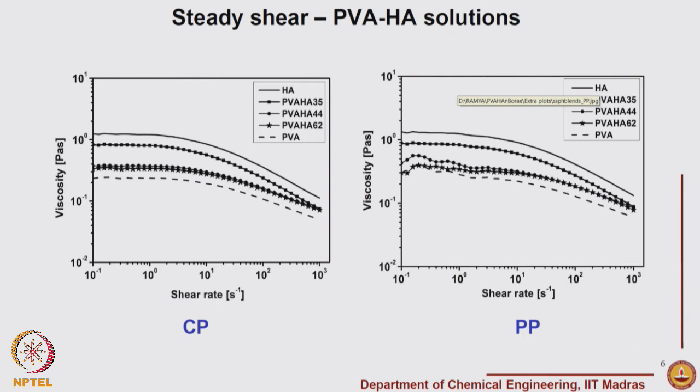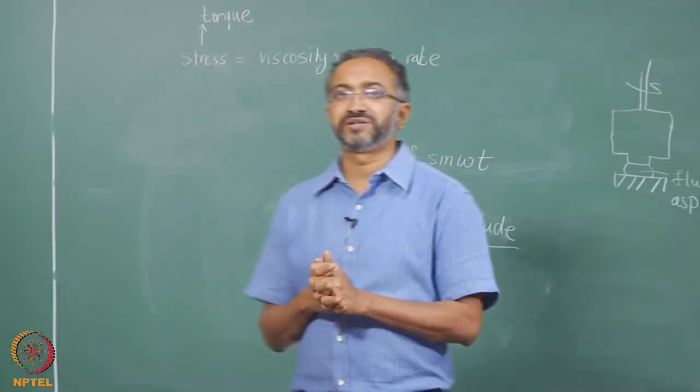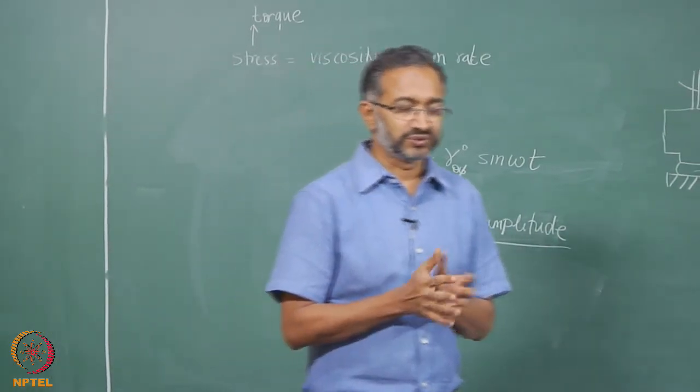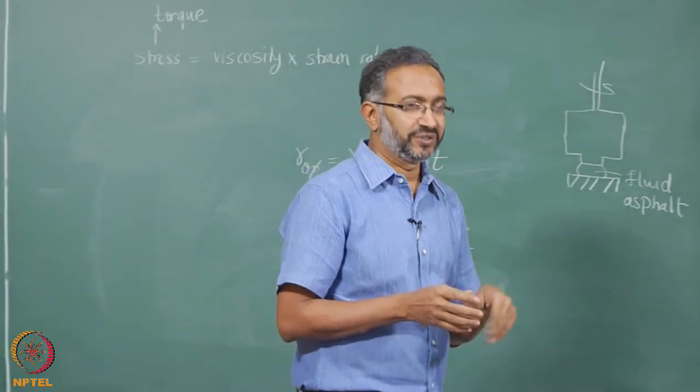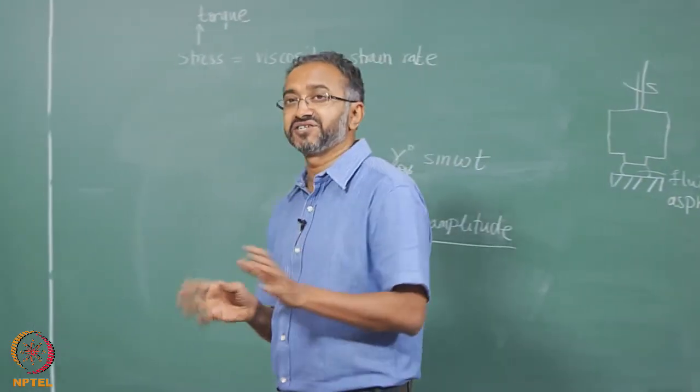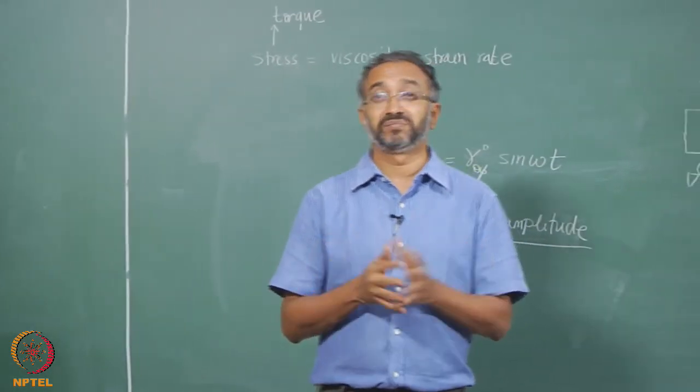So that's the first observation, that it looks similar, and this is something we ought to expect, because in the end, using rheology, our idea is to characterize material response, and material response should not depend on the nature of the geometry being used or the overall details of the rheometric measurements. In the end we would like to look at viscosity as the property, and we would like to use the numbers generated in these tests for further calculations or estimations. So we are interested only in the viscosity itself, which is a material behavior.